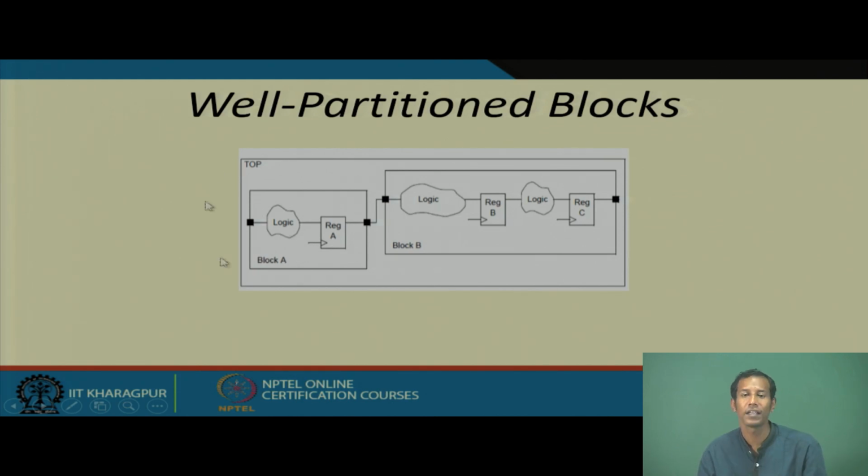So, the timing checks for block A and block B will be independent of each other and much more accurate, so that we can get the actual information in the timing analysis report. That is why, as a designer, whenever you are doing partitioning you have to be more careful to partition the design in a well mannered way, so that it does not affect the timing analysis further. We have to consider all these things in mind and carry on with our digital integrated circuit design.